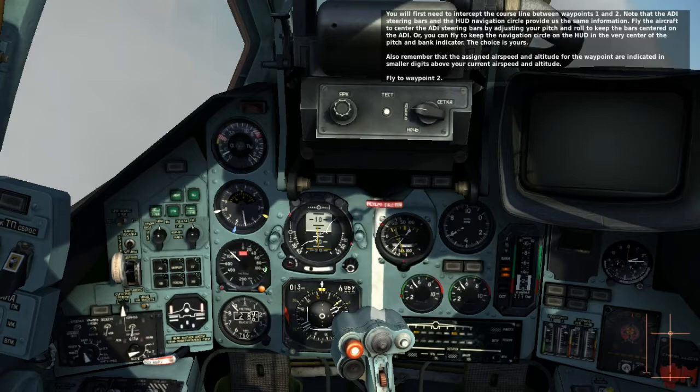And so I'm going to cheat. I'll be aiming for the course line as instructed, but since we have a while before we're going to arrive at the waypoint, I'm going to make the altitude change more gradual. I'm paying close attention to the left-right direction of the ADI and/or HUD, but simply losing altitude more gradually, which will give me better control of things. We just want to arrive at the waypoint close to the required altitudes so that we're ready for the next switch. And now, back to map.